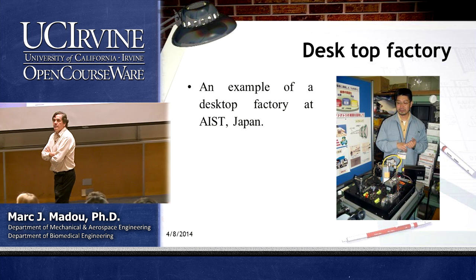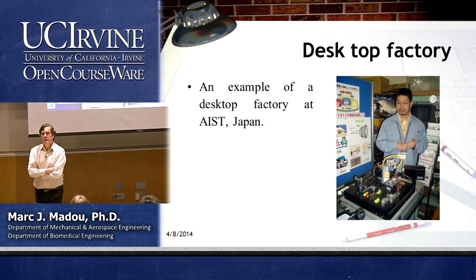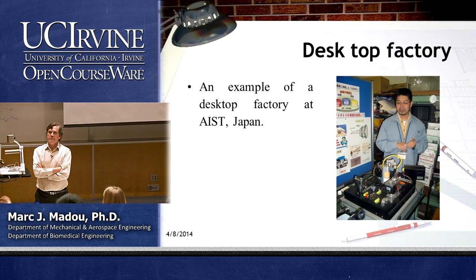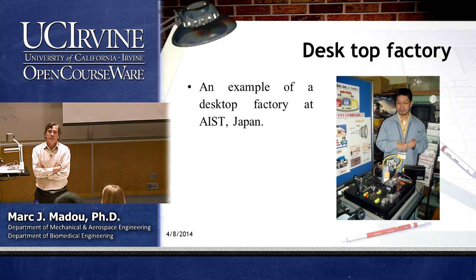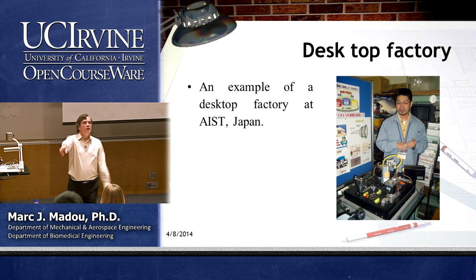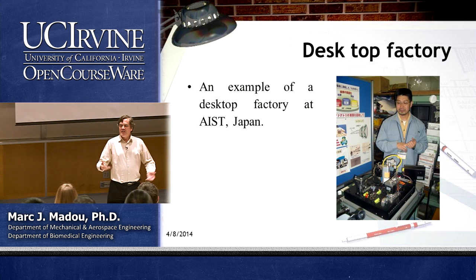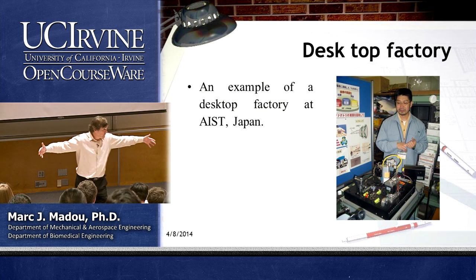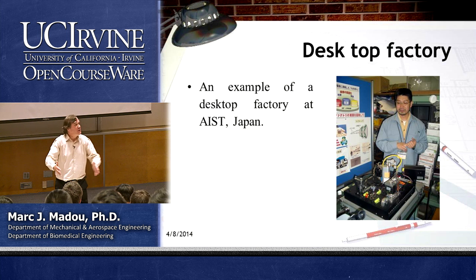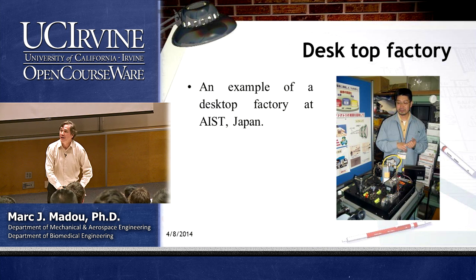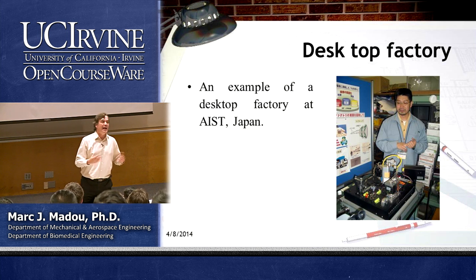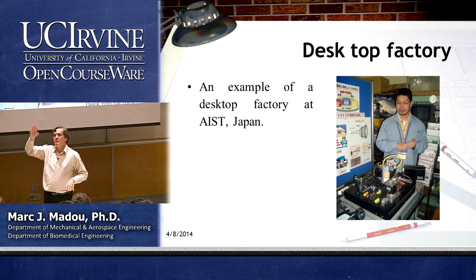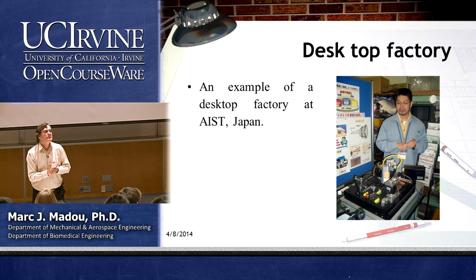Yeah. By reducing the weight of the tool itself, by reducing the weight of the micromachining machine, are we also reducing the relative tolerance that a machine can have? Yeah, that's a very good point, right? He's talking about that weight ratio. You know, if you make that very small thing, why would you have a machine of a ton? You cannot make the machine too small because it would become sensitive to vibration and therefore would become less accurate. So that's why people have studied that. They make kind of an optimum ratio for that.